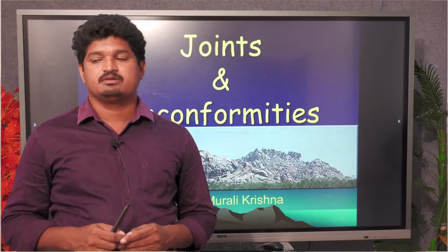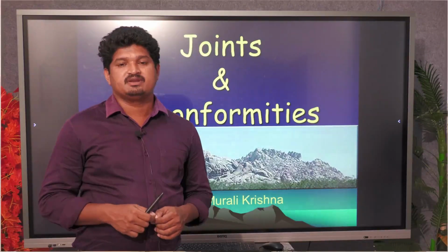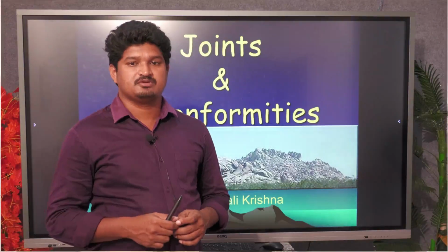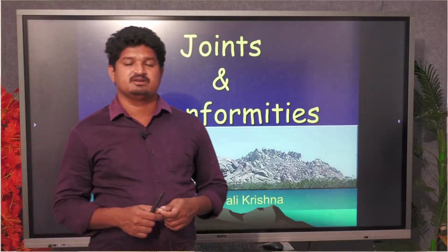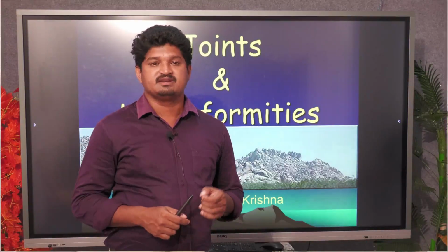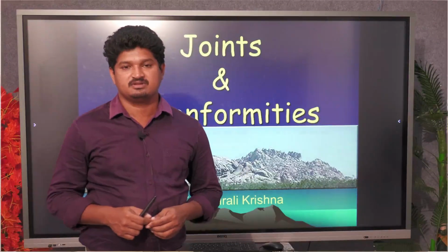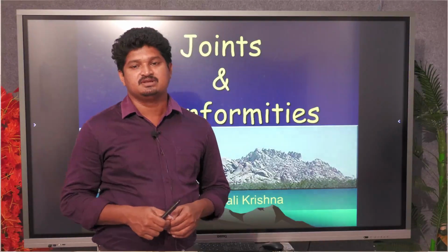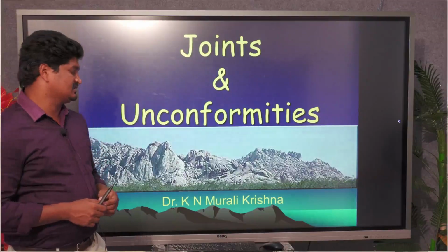Joints and unconformities play a very important role in civil engineering constructions, because of the identification of joints in the earth's surface area. While excavating material for construction, or when constructing reservoirs and dams, we may need to know which places have joints. In the future, cracks may develop along joints, and dams and reservoirs may leak. In that context, every civil engineer should know about joints, and similarly about unconformities also. So today's session is on joints and unconformities.